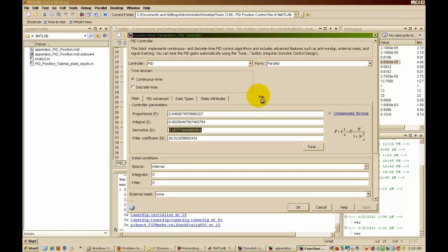Always be aware of your battery voltage when you're tuning. That's probably the most common problem when tuning a controller, because you probably spend 15 or 20 minutes tweaking gains and trying to get the perfect controller, all while your system is running. After about an hour or so, your battery is getting drained because you're pushing your motors hard, and you start to see your controller underperform, and you've changed your gain so many times that you're starting to get frustrated. The only real reason why your system is underperforming is because your battery is too low and that's not providing enough current to your motor. So always make sure you got a topped off battery when you're going to sit down and tune your controller.